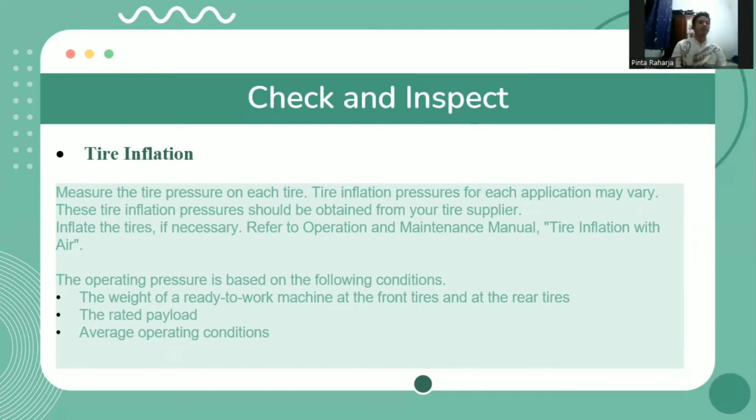I will explain how to check and inspect the tire inflation. Measure the tire pressure on each tire. Tire inflation pressure for each application may vary. This tire inflation pressure should be obtained from your tire supplier. Inflate the tire if necessary. Refer to the operation and maintenance manual.